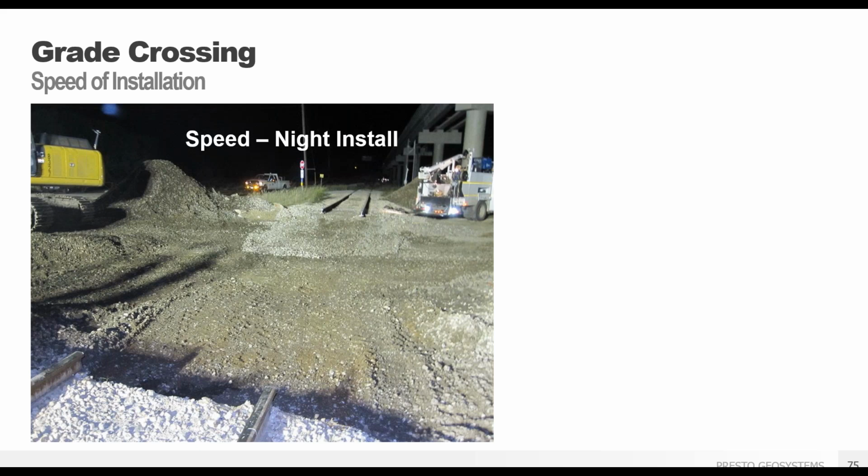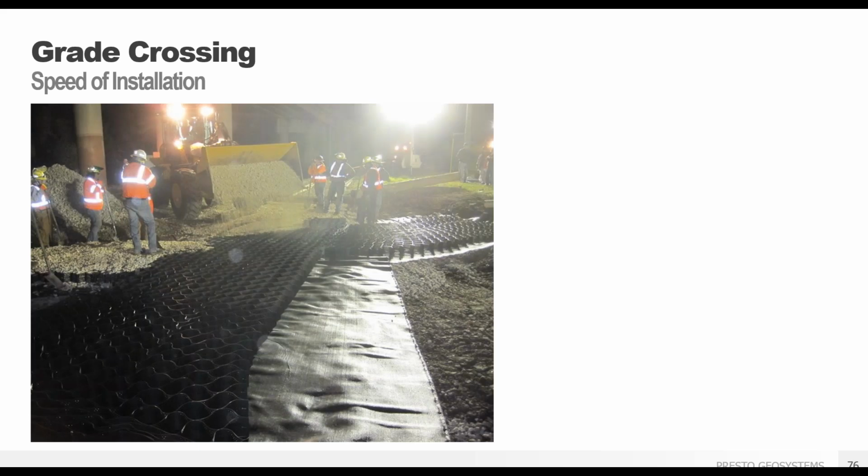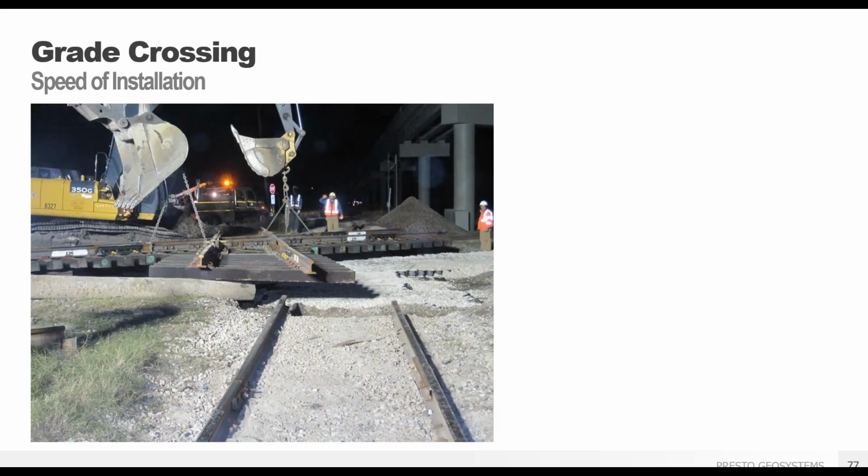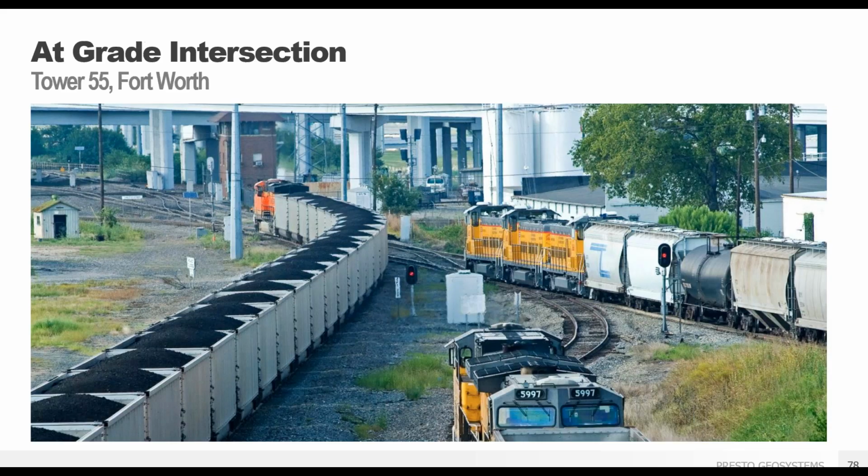You come in, you push the ballast to the side, you put down the geotextile and the GeoWeb, and like I said, we'll work with you on what type of geotextile and what geocell, and then put the ties back, and you got a crossing usually less than 6 hours from start to finish. So I've been on a lot where we start at 12 o'clock at night, we're done 4, 5, 6 in the morning. So once Sunday rolls around, that system's back in operation.